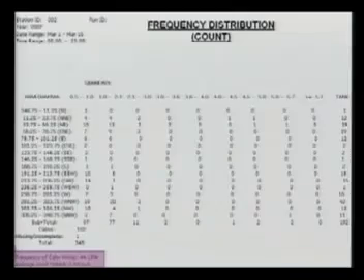So what is normally done is what we plot or what we develop. Nowadays the computer will do it, but what we develop is the frequency distribution, and here in fact we should call it joint frequency. What I mean by the joint frequency is, on this direction, you can see my arrow, I am plotting the wind direction. Recall the directions we measured as north, northeast, and so on. So here we are indicating the wind direction, and on this side the wind speed I have classified in different groups.